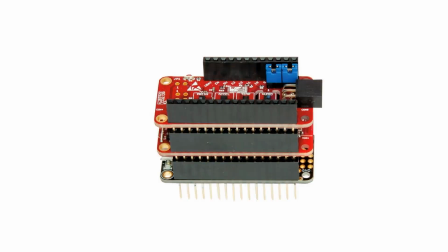In order to verify this relatively simple I²C simulation, we needed additional measurements, and these were performed on a Würth Elektronik Sensor BLE Featherwing kit. This kit consists of a master board, which contains the microcontroller. The other two contain a Würth Elektronik Bluetooth module and various Würth Elektronik sensors, such as 3-axis acceleration, temperature, humidity, and pressure. The master board communicates with the other two via the I²C bus at a maximum data rate of 400 kilobits per second.